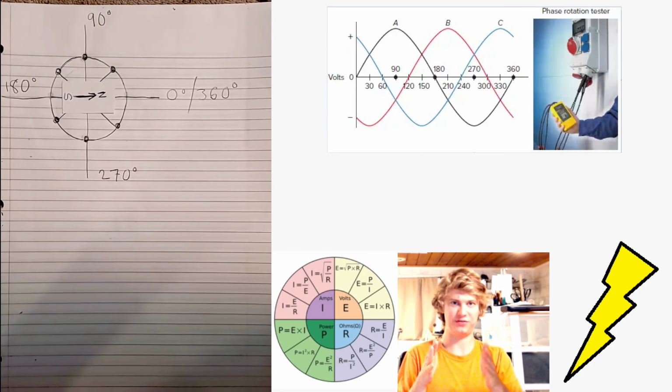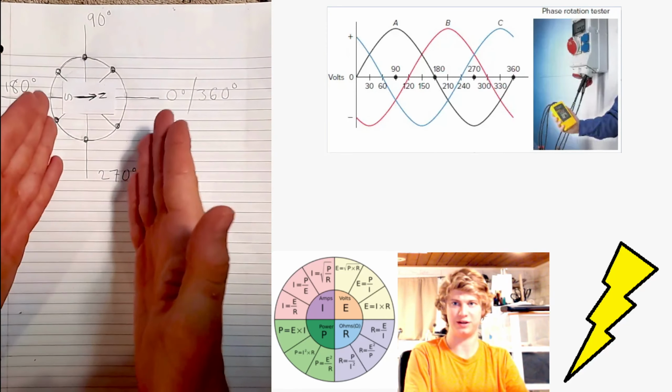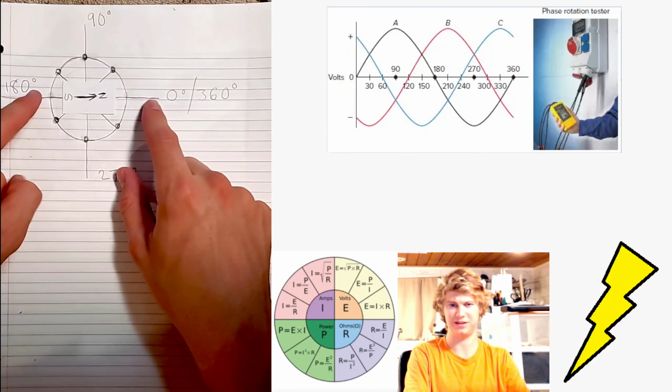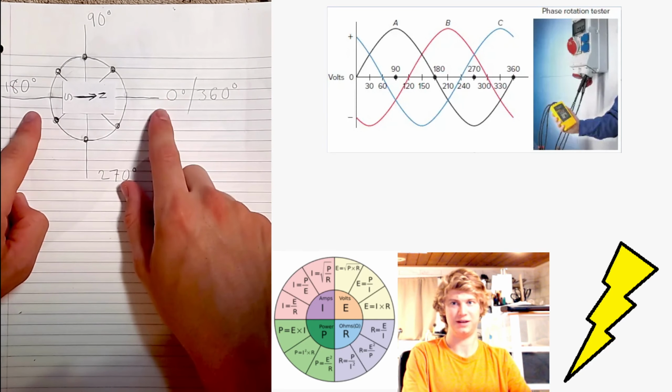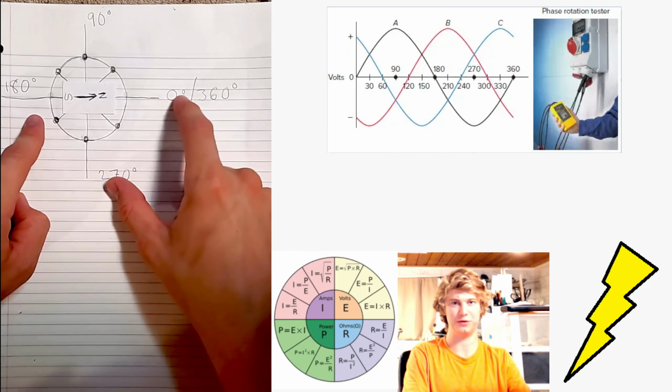It's like where you see where the A phase goes down to 180 degrees, where it goes to the 0 crossing again. You can see right above that where the B phase is. That kind of gives you a reference to where the C phase is in the very beginning of the graph, where the A phase is at its actual 0 point, and you see the blue above that. Okay, and again, remember, there's no conductors at this point. So we're not at any actual conductors, but we are close to the conductors. And again, even though we're at a 0 point, right here we're looking at just the A phase, we can see on the graph that's not what's happening with the other phases.